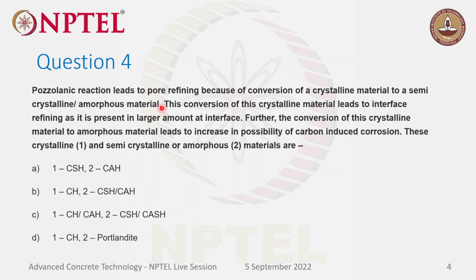And then what do the aluminate phases react to form with calcium and silicate? That is calcium aluminate hydrate. If gypsum is not there, it will form mostly that, but if gypsum is there, then it will form ettringite and monosulfate phases. So AFM means monosulfate and AFT means ettringite phases.